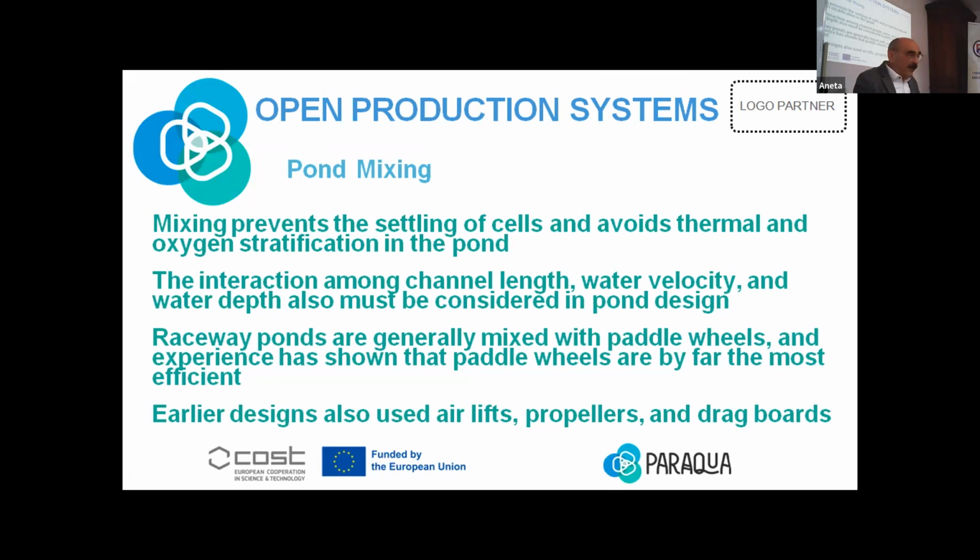Raceway ponds. Raceway means narrow, long ponds, where the mixing is with water velocity, generally with paddle wheels. In earlier designs, they used airlifts, propellers, and drag boards. A drag board is like a board you have in the pond, and you just drag it through the pond. It doesn't touch the surface, and this is how you mix. It's very efficient if we're talking about mixing, but it's very difficult to manage.